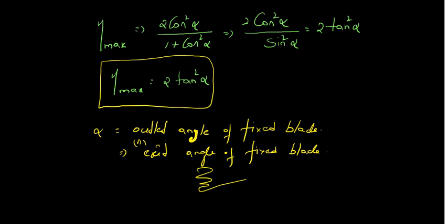the reaction turbine. Right? And now take time to recollect what are all the things that we have discussed under reaction turbine. Right? And shall we have a quick recap on this? We have derived the relation for work done per second, and the expression is in terms of m multiplied by (VW1 plus VW2) into U divided by 1000 kilojoule per second. That is the first relation we have derived for the reaction turbine.